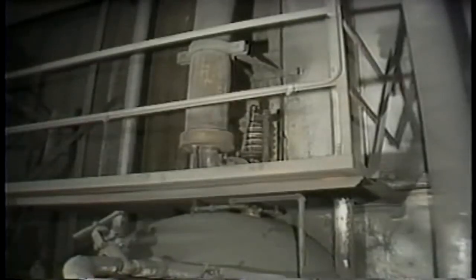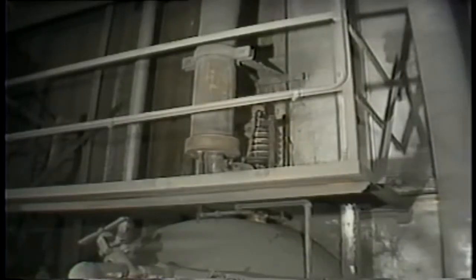On drum-type boilers, safety valves are also installed on the steam drum. Safety valves on the steam drum lift if the pressure in the boiler exceeds designated values. This can happen when there is a decrease in steam flow without a proportionate decrease in fuel and airflow. If the demand for steam decreases, yet at the same time the boiler is being supplied with fuel and air at a rate greater than demand, the temperatures and pressure inside the boiler may exceed appropriate values for normal operation. In this case, safety valves on the steam drum may lift to relieve this pressure.